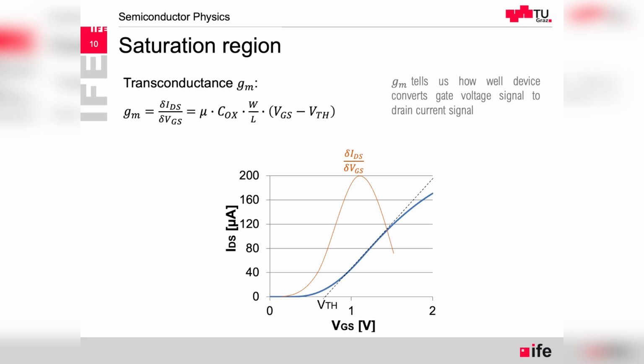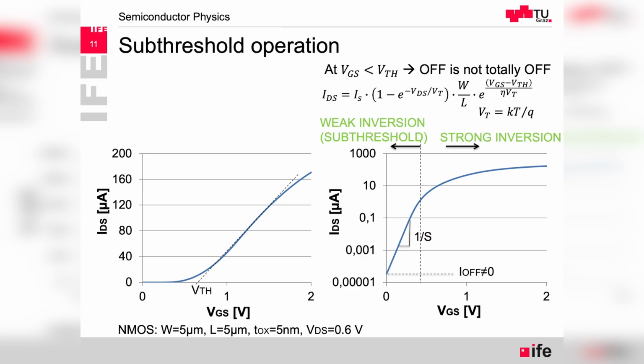And then the current that we have to read out, we can run this current over a certain larger resistance and then connect an analog to digital converter, but the voltage drop will be much larger on the output, large resistance times the large variations of current, than the input signal. So that would be our idea of using the transistors, and we always want to think about this parameter to be of large value.